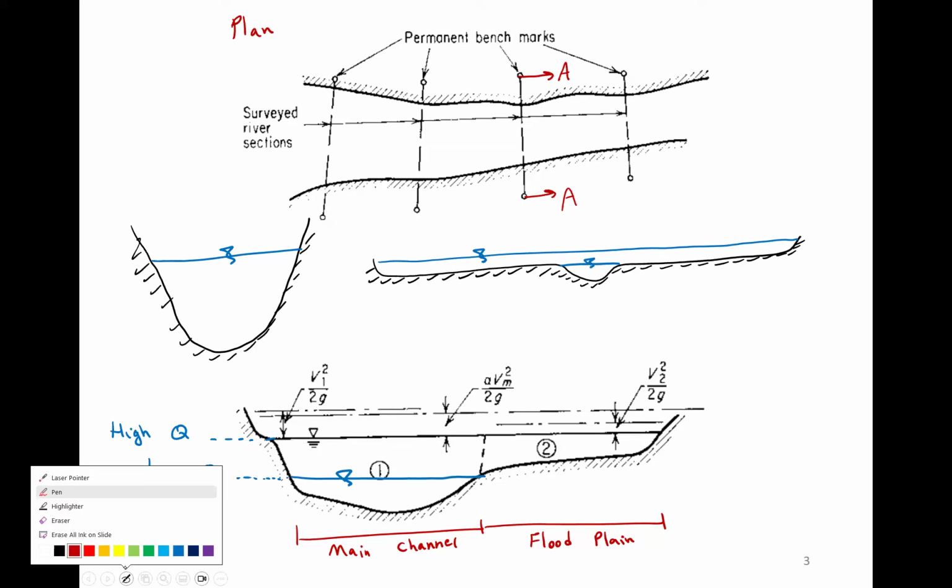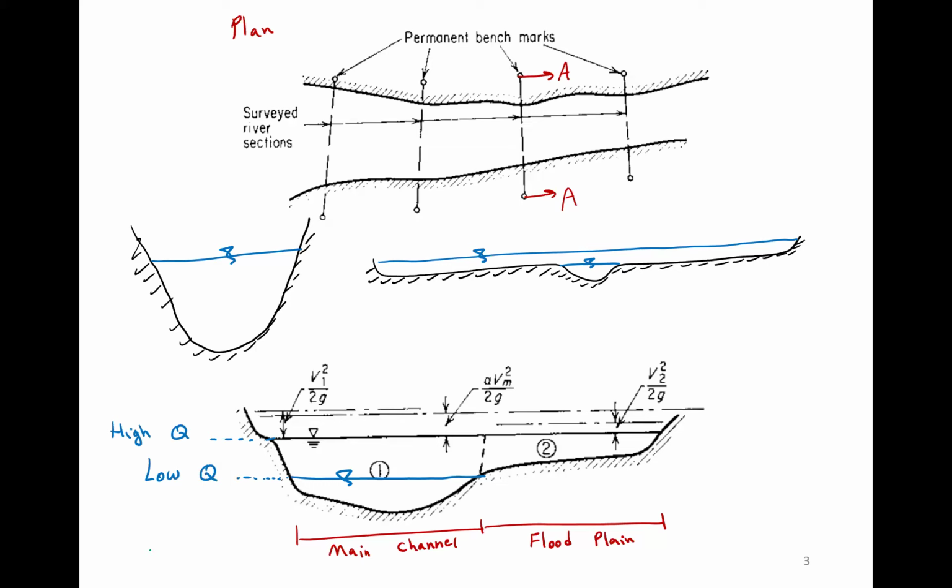And in many cases, we see some infrastructure built to contain the flow in the main channel and minimize or sometimes eliminate the floodplain. For example, we build almost a wall here, let's call it a wall, to block the flow into the floodplain, and we call it a dike. Again, this is something we see a lot along the Fraser.